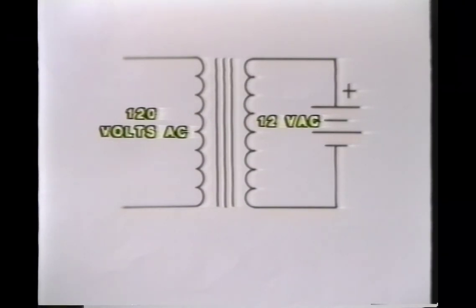Let's look at the schematic diagram of the 10 to 1 transformer with the 12 volt output connected to a discharged automobile battery. Knowing that current flows from positive to negative, according to Benjamin Franklin's concept of conventional current, we can predict what will happen in a circuit by looking at the schematic diagram. Remember, the transformer's output is alternating current. The transformer is strictly an AC device. It uses alternating current as an input on the primary and produces alternating current as an output on the secondary.